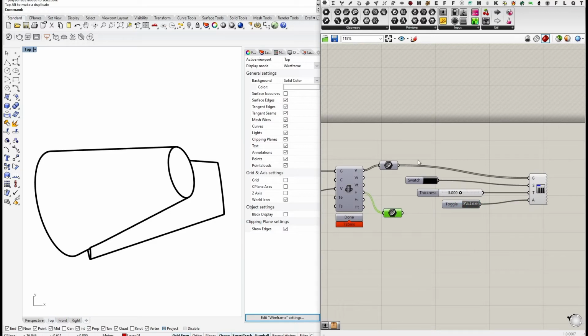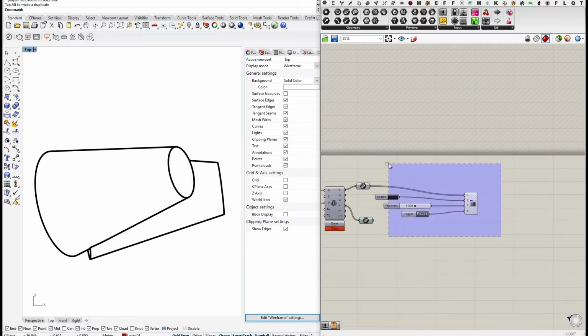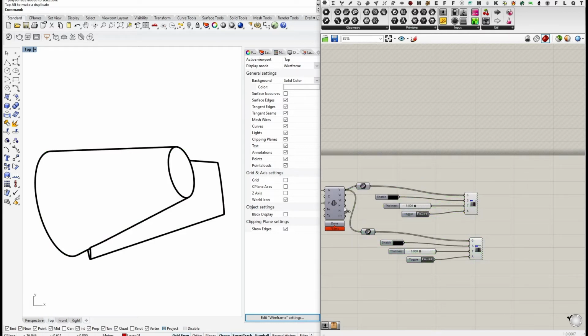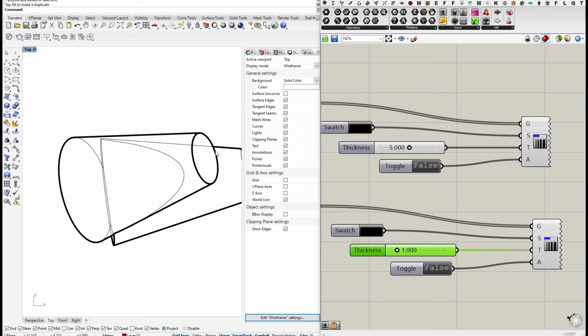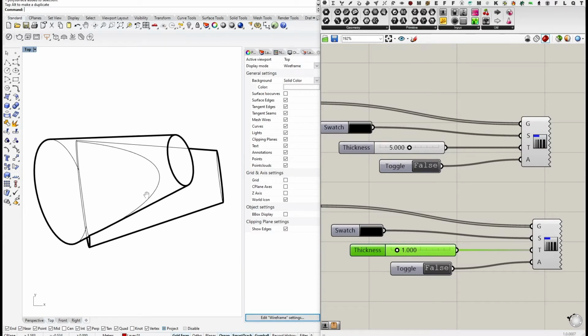We now defined our visible lines, and now we want to define our hidden lines. So to make it a bit easier, we can quickly copy paste those components and first plug them into the hidden line tab. So now it becomes a little bit illegible, like what is hidden, what is not. The first thing we can do is we can reduce the line weight of the hidden lines so that we see, okay, the hidden lines are now the thin ones that disappear from the visible ones.